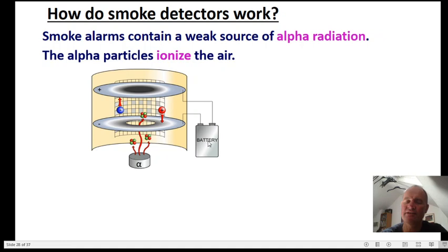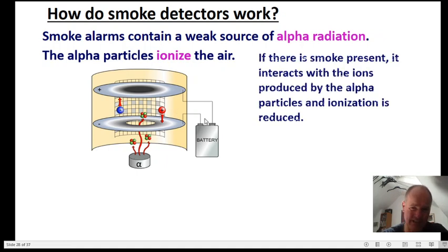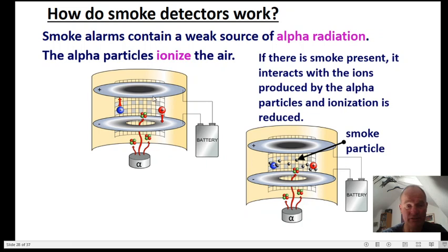And if you use a battery, the special type of batteries that they have in smoke alarms, 9-volt batteries, 9 volts is a bit higher than most normal batteries, which are about 1.5, it contains a potential of plus and a minus between 2 plates. And these ionized particles caused by the alpha can then move. As the charged particles move, positive to the negative and negative to the positive, that's effectively a flow of electric current. And the flow of electric current basically keeps the alarm off, because there's an electric current of ionized particles flowing between these plates.